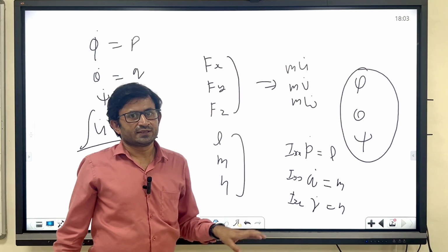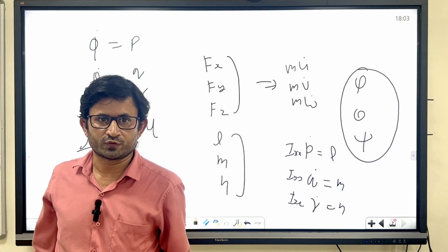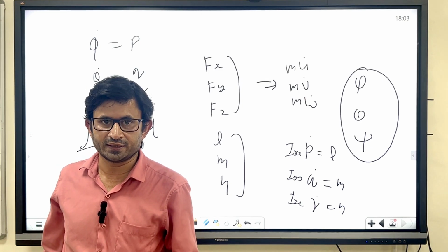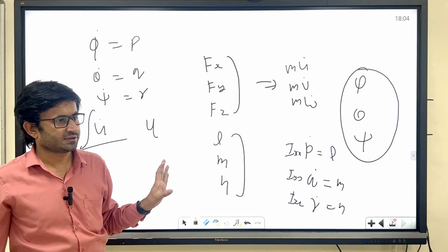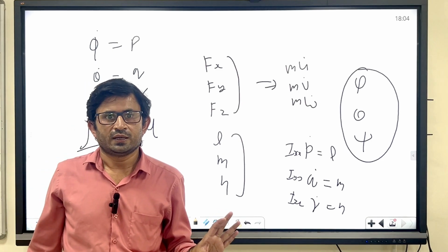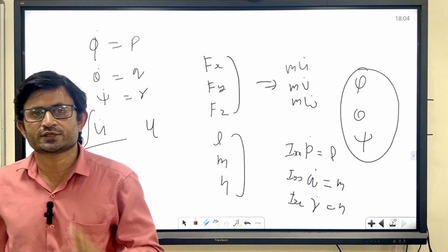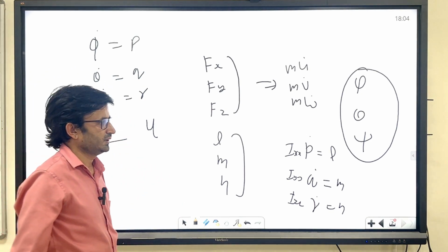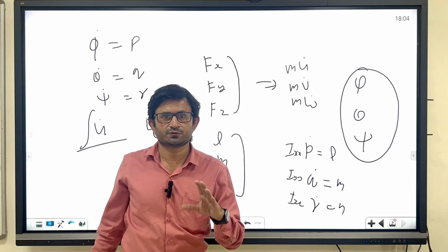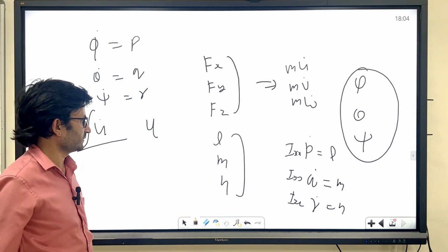The purpose is, you can write the equations of motion in any framework. For example, I have written them in MATLAB. You can integrate, and you can check whether your aircraft is behaving well or not. And here you will give some input. That means here you are checking the natural response of the aircraft, not the forced response. In the autopilot course, I will cover the forced response, where you will use the autopilot in order to navigate from one position to another position.